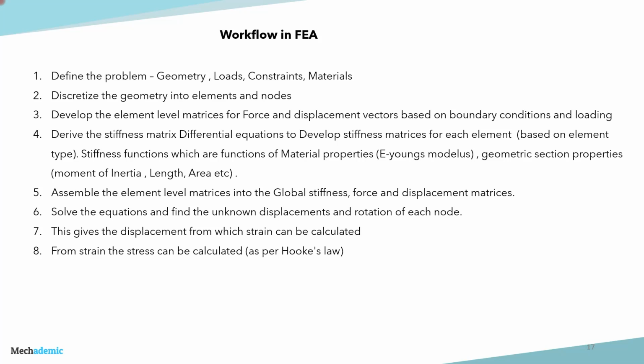Then what are the boundary conditions or constraints we need to apply to that model? So let's say if you have a bracket, how is it attached to the frame? Whether it is welded to the frame or whether it is bolted to the frame. So based on that, the nodal constraints which have to be applied on the model are decided. And then of course the final one is the materials, the material profile of that bracket.